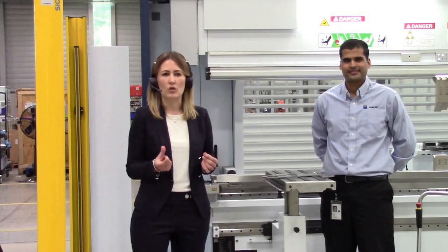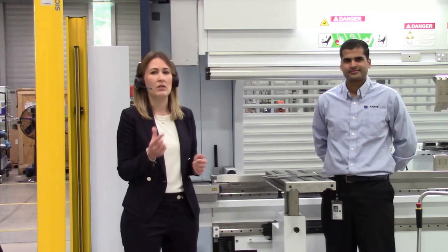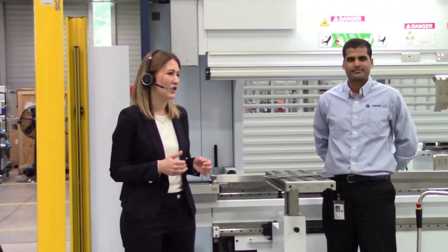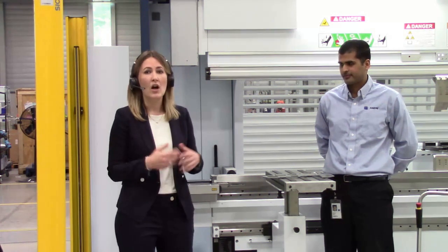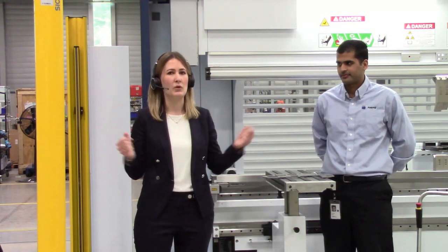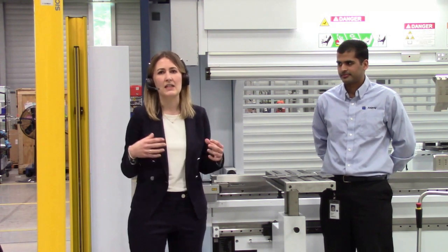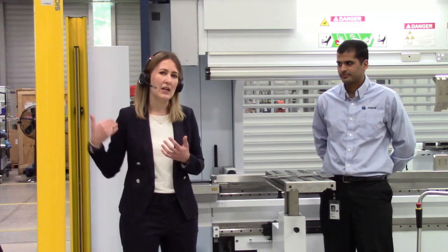ACB hard tools, for example, is excellent for very short flanges because the ACB laser will, depending on your die width, require a certain flange length in order to read that line that the laser is projecting. So short flanges would be a perfect application for hard tools. Also, very long tools, you can have multiple hard tool setups, and the ACB laser can do that as well, but it will take just a little bit longer to do that reading.